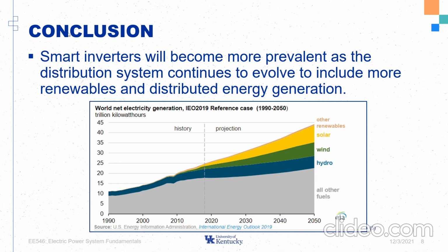To recap, in this presentation, we have discussed the working principle of a smart inverter. In addition to converting direct current to alternating current, a smart inverter has the added capability of monitoring the voltage and frequency of the power in the grid. In this way, the smart inverter acts like a traditional load frequency controller. Not only does a smart inverter help ensure power quality, it also provides the system with added resiliency to faults.